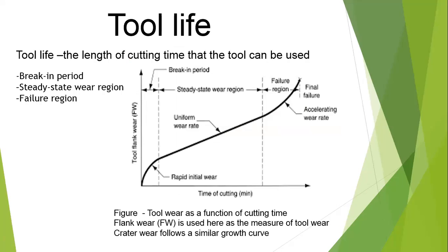Tool life. The duration for which the tool performs as a cutter, the time is known as tool life. There is a figure of cutting time versus tool flank wear. It can also be crater wear, which is characterized in the same figure.